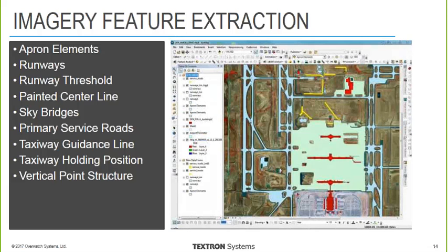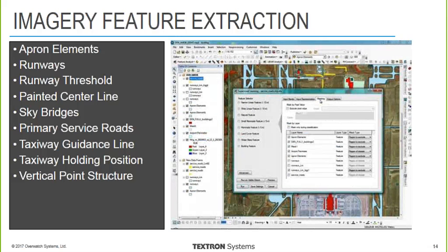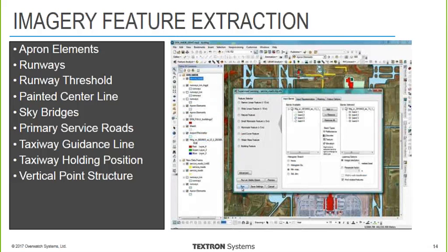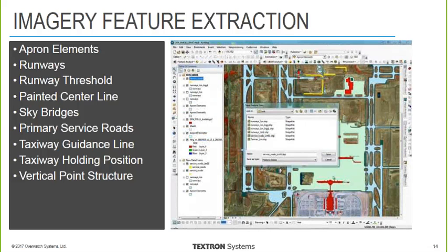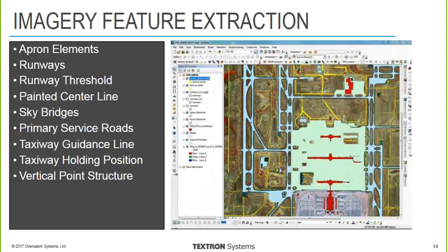So now we can change our 4-band data to show the near-infrared band. That's going to help us isolate classes such as roads. In this case, I've used lines as training examples. We're going to mask out the rest of the layers. The lines work really well for training examples to get these types of linear features. We're going to try and get a good representation of the road network, and then we're going to convert those polygons to lines. We're going to straighten those lines, and then we can add metrics and attribution to that so we can compute length. So we'll know how many segments we have, and we know how many miles of roads we have. Again, we did this just in a few minutes.